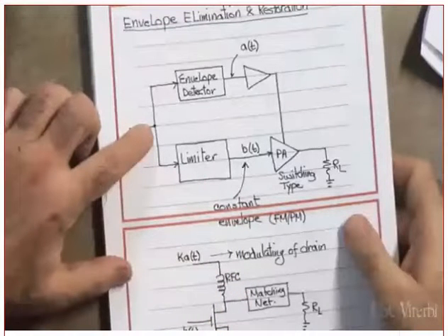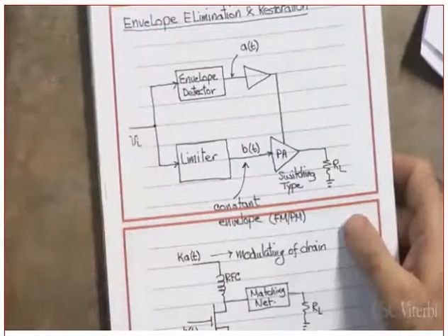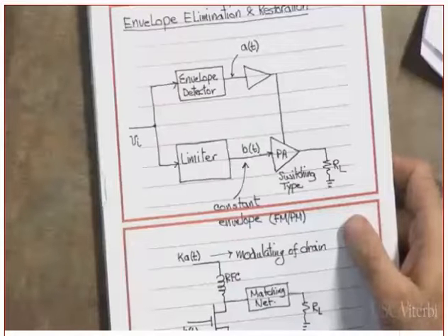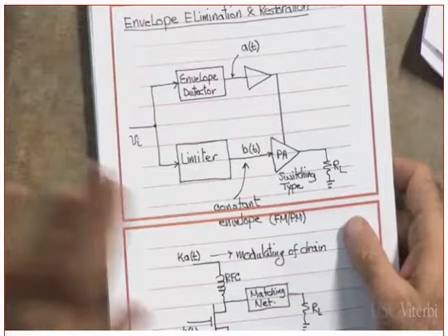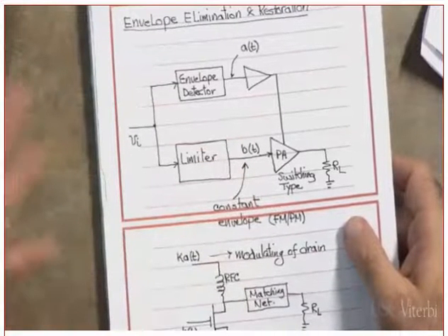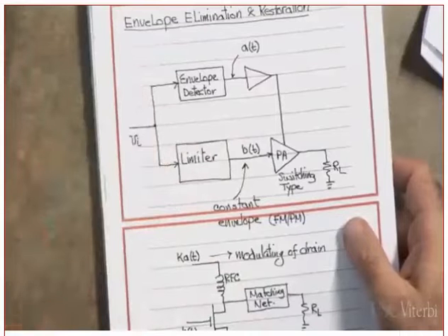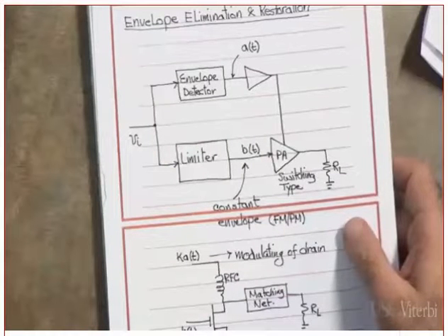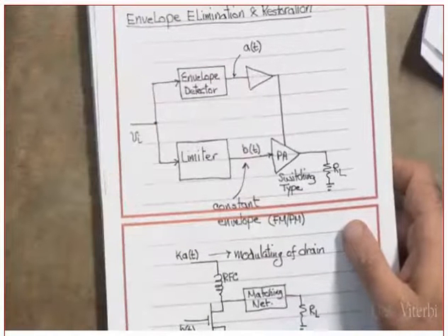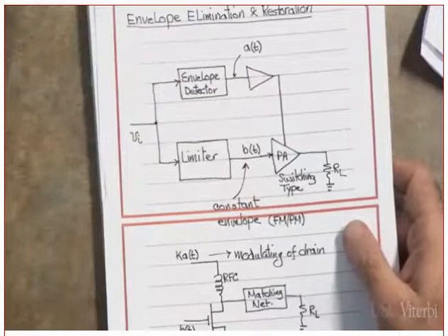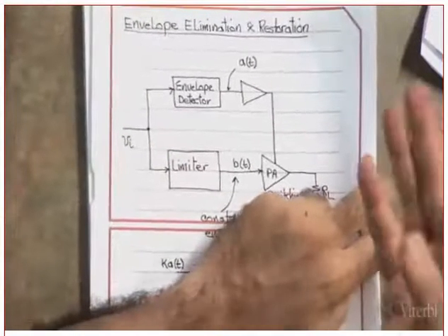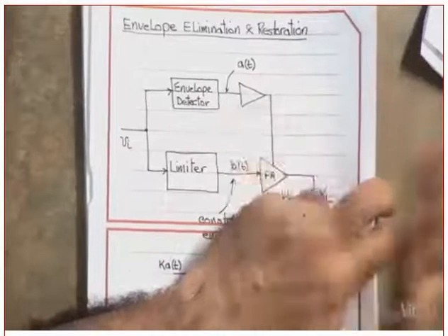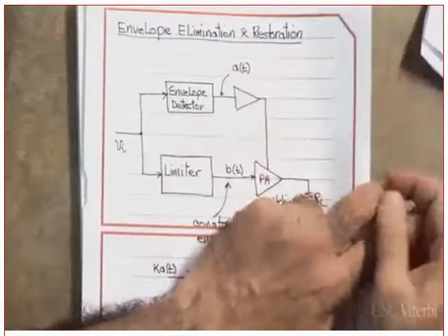By the way, is it possible that we don't have AM modulation? It is possible, but because the signal has been propagating, are you following me or not? It might be received with fluctuations. Clear? But here we are talking about at the transmitter side. So we are putting AM modulation. If you look at an FM demodulator, you will see a limiter at the receiver. Why do we need a limiter at the receiver in an FM demodulator? Because when the signal propagates, the amplitude is no longer going to be constant. You would like to cut all of these clippings at the beginning, before you go into